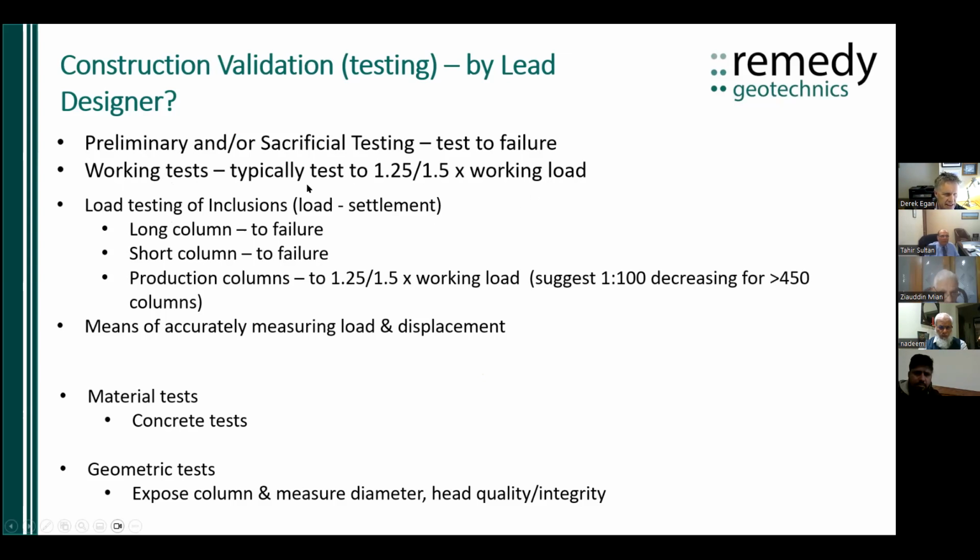Now, when you're load testing the inclusions and doing the preliminary or sacrificial testing, it's not unusual to do some long columns, which are the design length, and do some short columns that are just within the soft ground. Now, the purpose of these columns is to try and assess what the soil to concrete shear stress is going to be in the zone of negative skin friction.